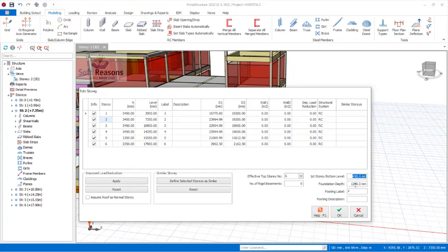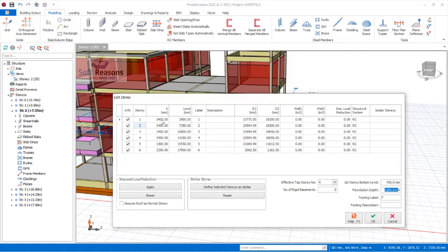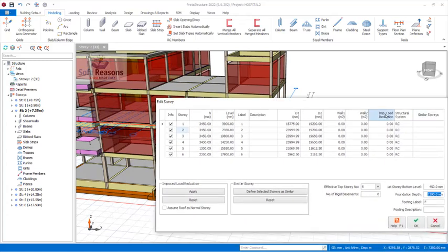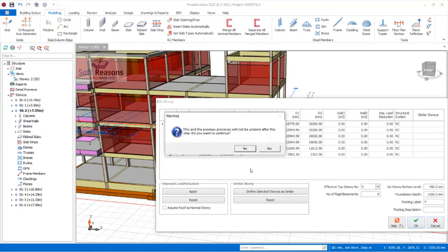So if you sum this up, you will be having 1.65, or 1,650 millimeters foundation depth. So this is where our concern is. For us to be able to have this placed successfully, we need to subtract this out of the story height for the foundation that is not on a normal default story level. So we will get rid of this, click on the OK option, yes, options.